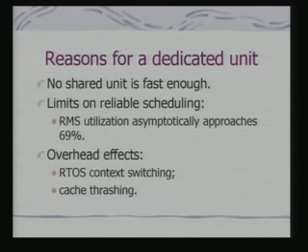Because of the context switching overhead, I might not be able to meet my timing constraints when we are using one CPU and mapping multiple tasks on that CPU. At the same time, there can be cache thrashing. That means when we are switching from one task to another, I might need to reload the cache memory. So there will be misses and hits at regular succession.